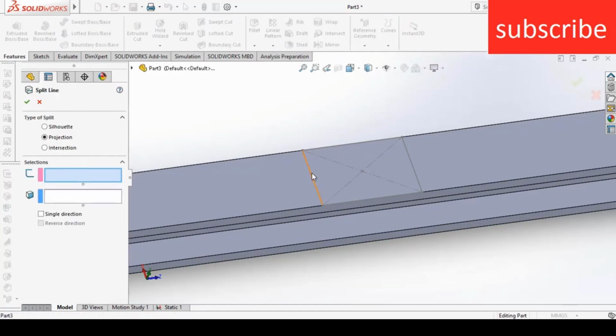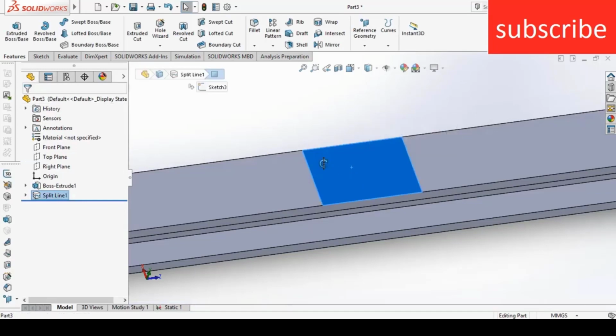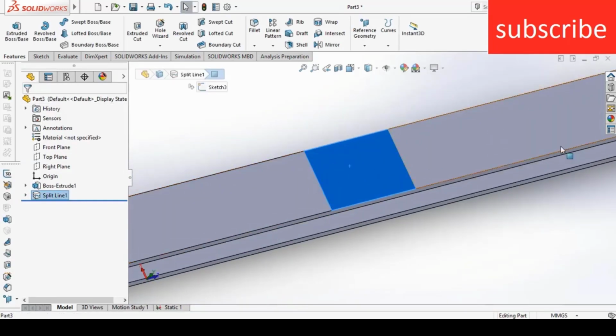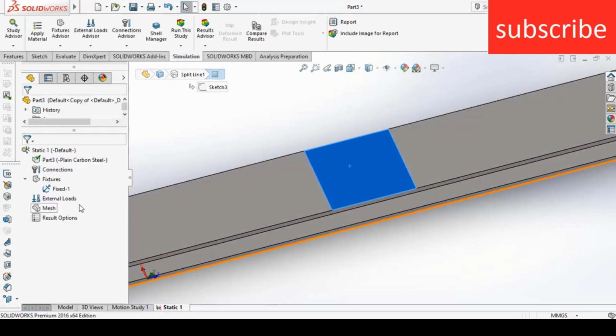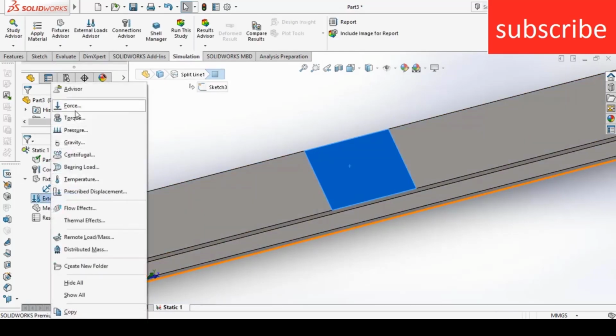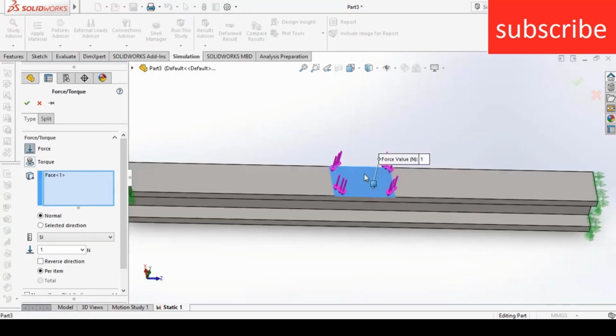So select split line, and after that select this face, click OK. As you can see, now I'm selecting this line only, I'm not selecting this whole beam. Go to SolidWorks Simulation, sorry, static. Now click on external loads, click on force, select this face. As you can see I'm selecting this face only.